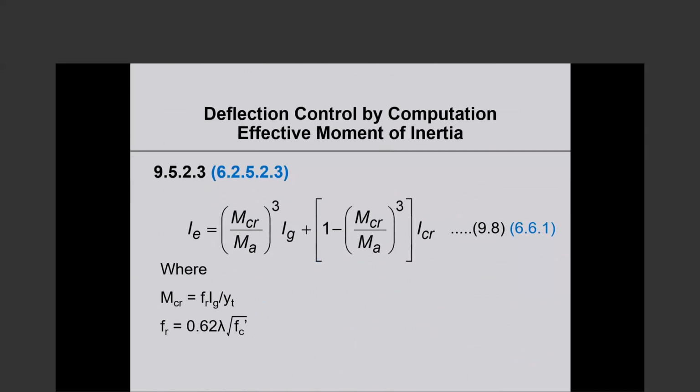Yeah. So there is one question: is long-term deflection automatically computed in the result of an FEA model? That you have to see which software you are using. Most of the software will do basically the same thing that Dr. Ghosh said. They will estimate it. It's not calculated. You cannot calculate a long-term deflection just like that. So that will be estimated based on different formulas, and you have to see if the software does it automatically. Most of the software don't do it automatically. You have to check a button or something to calculate long-term deflection. So be sure about that.